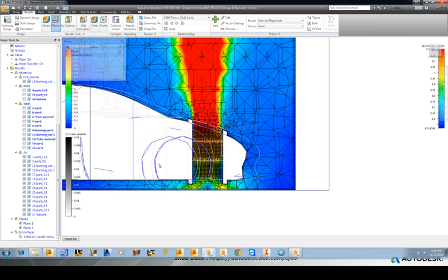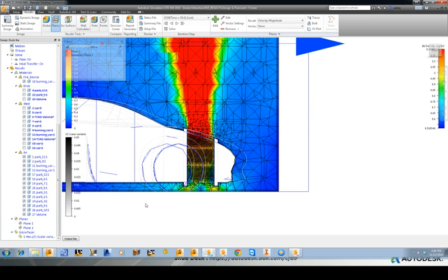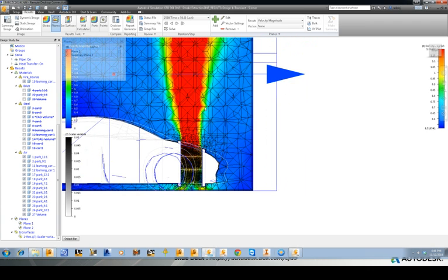Okay. I'd say that my mesh was too coarse here. My main focus was to run a model that had some good results that I could show everybody. But as a general rule of thumb with any CFD model, through gaps we want at least 4 or 5 elements from one face to another. If we take a look at the bottom, just underneath the car, excluding the boundary layer, we've got 2 elements. So our mesh is probably half as fine as it should be, and we can see the plume, like you say, Royce, follows very much the lines of the elements.